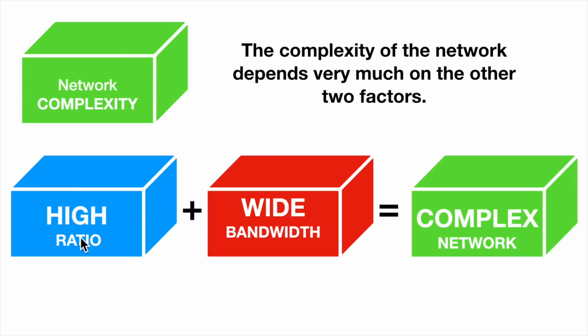Now, there are some ways around this, and in the next video I'll talk a little bit about it. Instead of saying, well, maybe we can't go down from 50 to 2, maybe we could break that up and have some intermediate virtual resistances that we match to, and stack some L match networks in series one after the other. You can do that and break it down, which will give you a lower Q and a wider bandwidth. But of course it greatly increases the complexity. So you see what I mean?